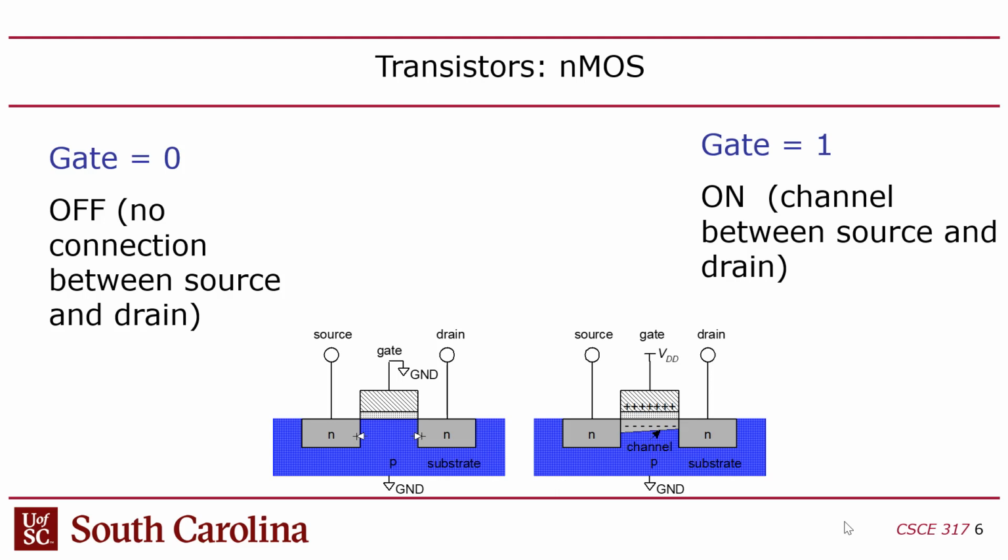So if you ground the gate, or if the VGS is less than the threshold voltage, which is usually like 700 millivolts, then the transistor is off, right? So what you end up with is that you've got the source and drain, and it doesn't really matter what voltage you've got those at, because the substrate voltage is ground, is at 0. So that creates a reverse bias diode. The diode is from P to N, where P is the anode and N is the cathode.